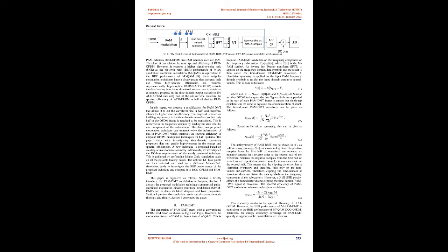However, the optical signal output of a conventional LED can only be real-valued and unipolar. Therefore, the modulation waveform needs to be both real-valued and positive. Hermitian symmetry is usually used in conventional direct current, DC, optical OFDM to enable a real-valued output of the OFDM modulator, whereas a DC bias is usually added to shift the negative samples of the waveform to become positive.